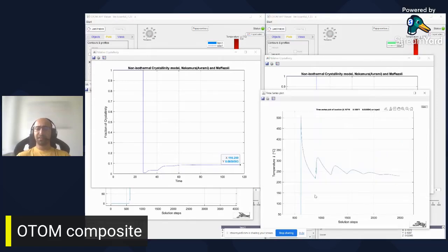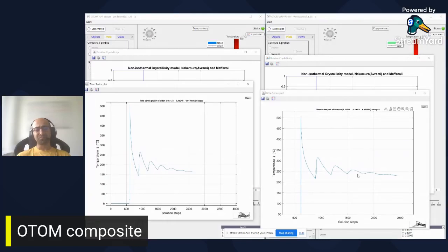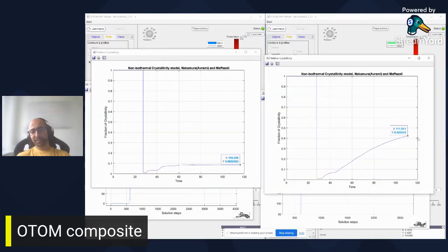So almost 4 or 5 times more crystallinity based on the fixed tooling of the 140 degrees Celsius. And the reason again is because we are very close to the middle range temperature between the glass transition and the melting temperature, while here we are very close to the glass transition. So our material is more solid, and there would be less room and time for crystallization. So that's why we got more crystallinity here.